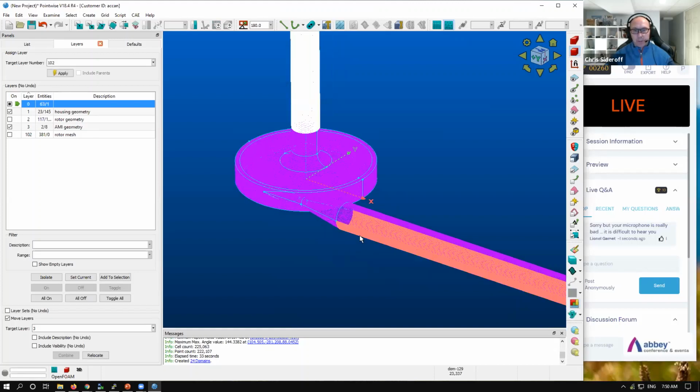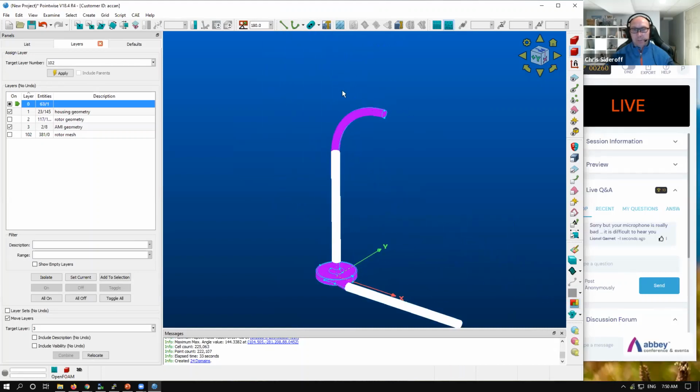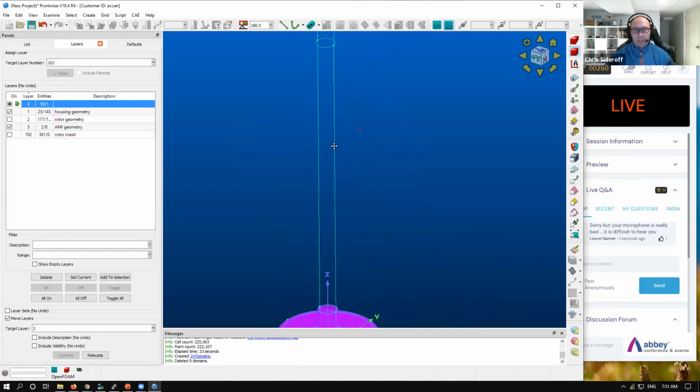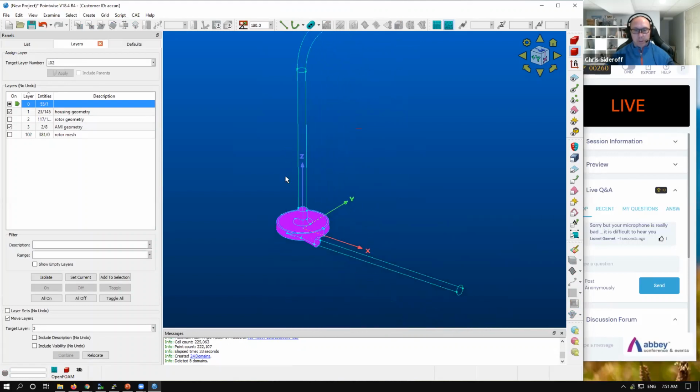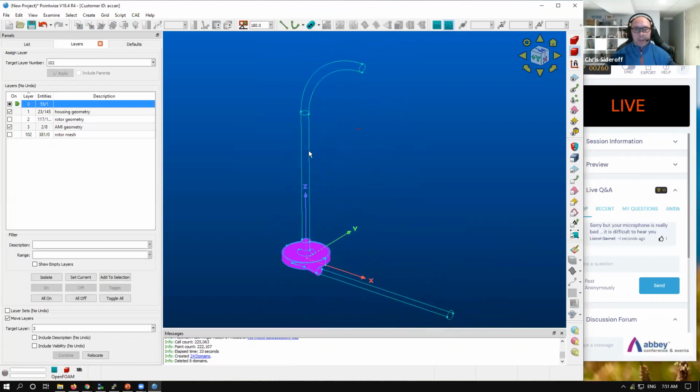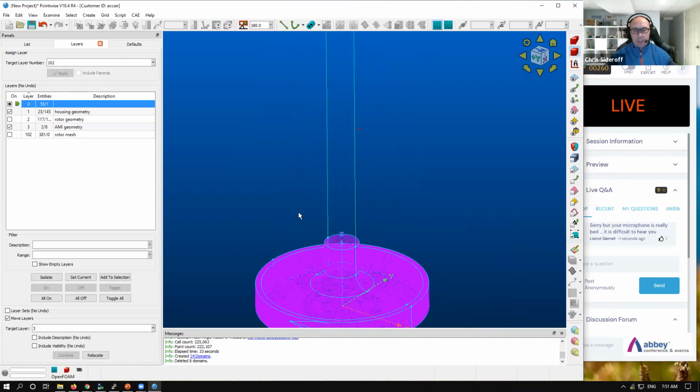So what I'm going to do is delete all these unstructured domains. I'm going to leave the actual connectors there, because I'm going to use these connectors to build the structured mesh. And I'm going to toggle the mesh type right now, to make sure that my structured mesh works. So I'm going to do a couple of things here.